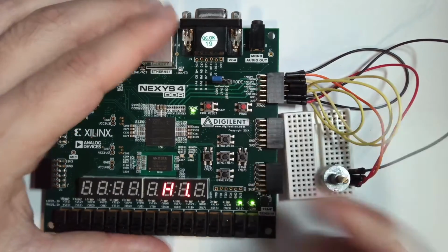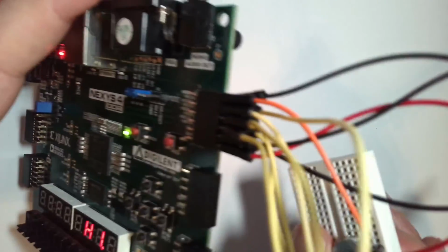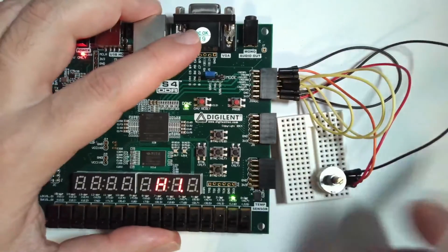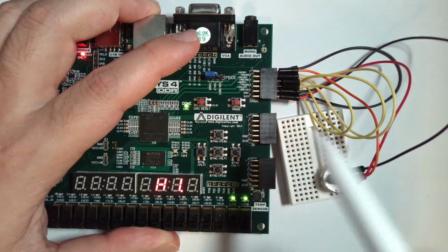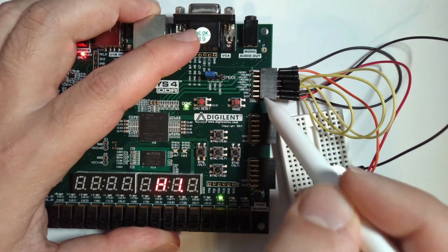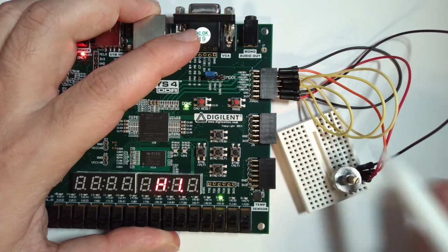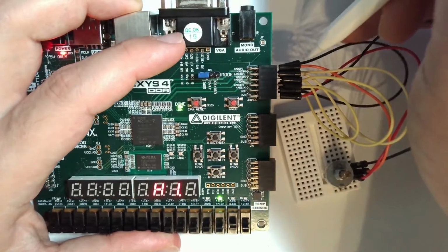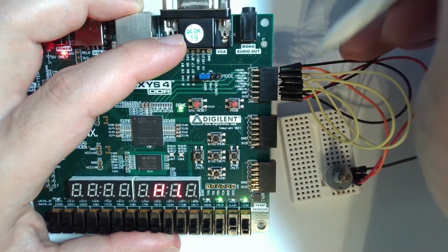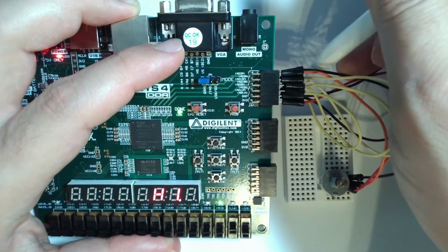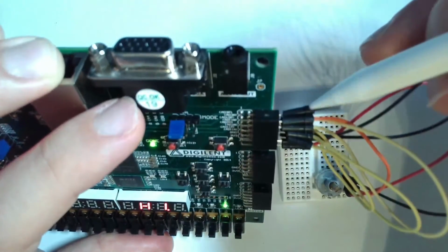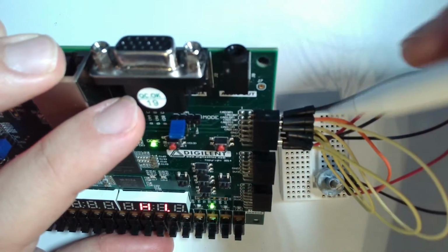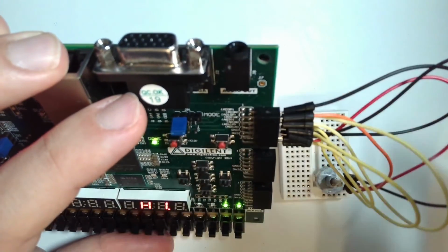And channel 0 as well, I don't know if you can see it in here, but channel 0 should be connected to the ground. So I took some of these black wires and connected it from the ground that is here, which is also connected to the ground of the potentiometer all the way in there. So the negative port, you need to make sure that you connect it to ground. This is one of the most common mistakes I've seen, that you don't connect the second one here to ground. You need to connect this to ground, and this is actually the signal you're trying to sample.